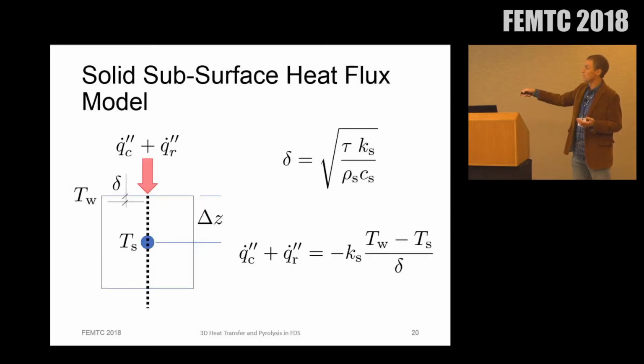So in the 1D model, the grid resolution gets set for you automatically based on a stability argument. This is like the von Neumann number for thermal diffusivity, thermal penetration depth if you have a time scale of 1. Okay, so this is how this cell dimension is set. And of course you can change this with cell size factor or what have you.